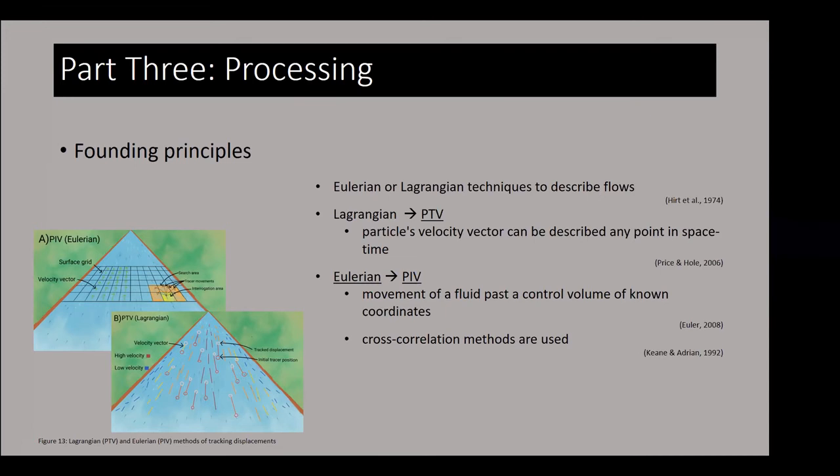So there's a limitation with Lagrangian techniques, as they have natural traces that aren't entirely stable in structure, and they're capable of deforming, breaking up, agglomerating, and they interact with one another. The problem is we're not yet able to define how those particles interact with one another mathematically. A limitation with Eulerian, however, is the reliability of the particles to remain steady throughout its gridded structure in terms of velocity, and that's just a basic fundamental to do with the mathematics and the assumptions that it makes.